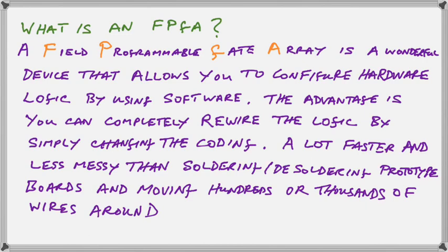Finally, we get to FPGA. What does that stand for? What is it? Well, a field programmable gate array. It's a very wonderful piece of chip that allows you to configure hardware logic using software. That's the best description, and I made it up just for you. The advantage is you can completely rewire the hardware logic by simply changing the program code and reconfiguring it.